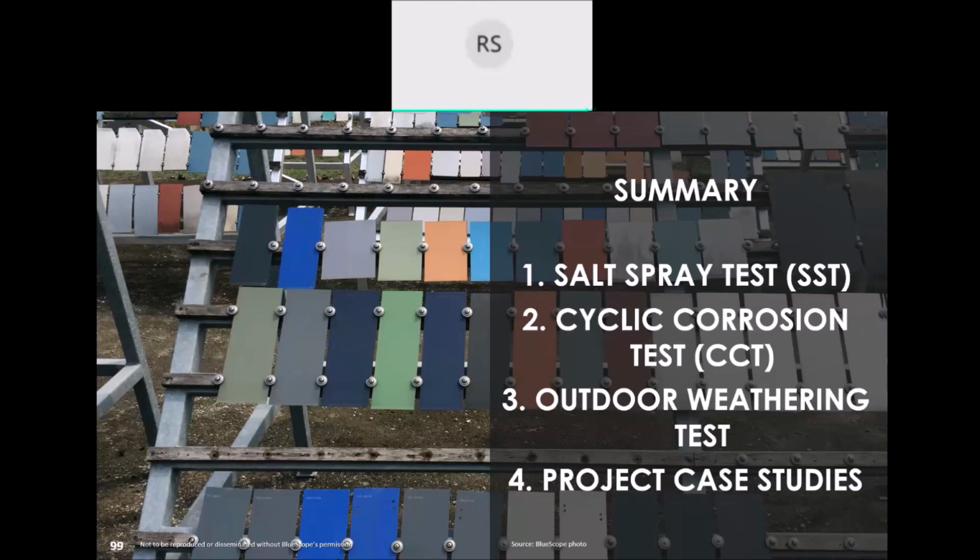If a certain company or supplier comes to you and says, hey, my samples have been exposed to this outdoor environment, which is classified C4, and this is the result, then you can get the direct answer from them. Instead of, hey, my material has been tested for salt spray, and this salt spray test has been classified C4. Do not trust that result, because that is quite misleading, right?